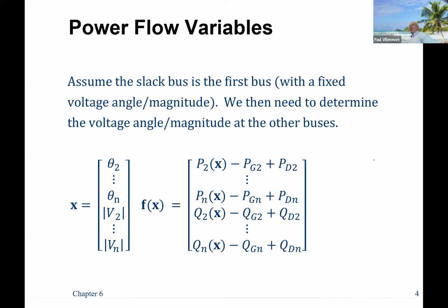Now, if you remember during lab and even during class, I was very specific about doing rows and columns. I said, make sure you do F1, your rows, F2, F3, F4. You do those as rows, and then your columns are your variables. Hopefully, you'll see why that's really important here, because these are going to be all my power balance equations. And then I have all my delta Qs. And for my variables, I'm going to put my thetas first, and then I'm going to put my voltages.